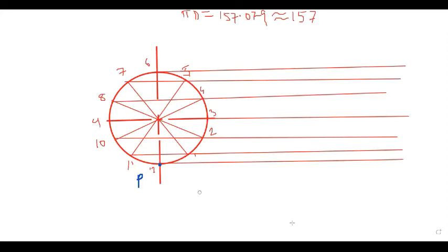So first we draw a line less than 90 degrees, of any length. Okay. And it is divided into 12 equal parts. If you divide the circle into 12 equal parts, you divide this pi d line also into 12 equal parts. Okay. So if we write this is P and this is P dash, so this is also P dash equals to pi d.